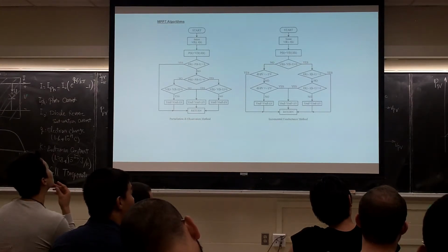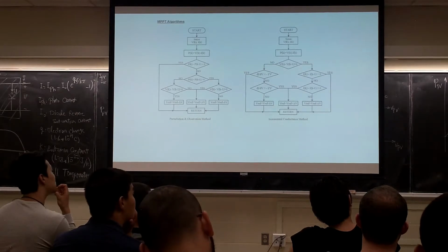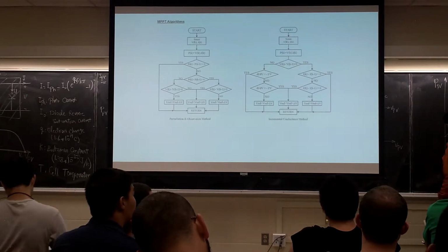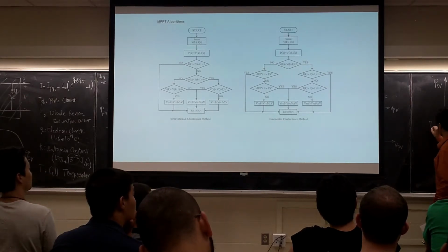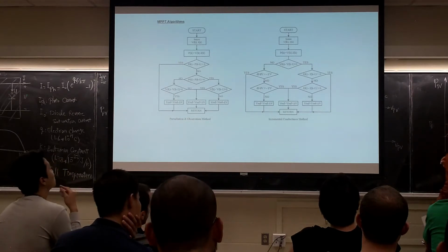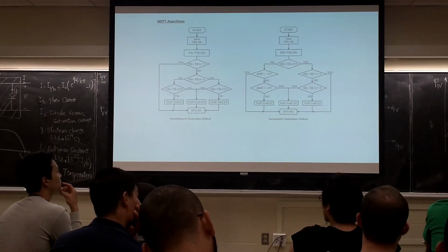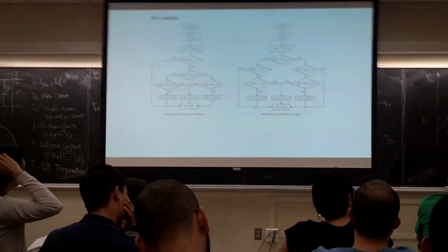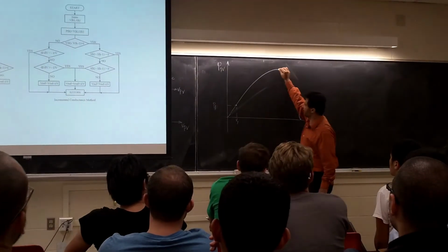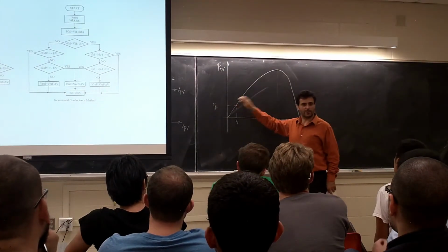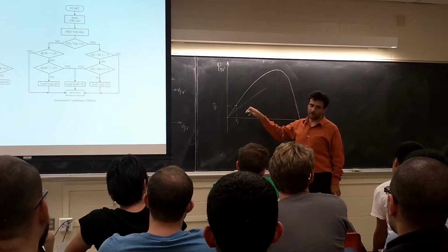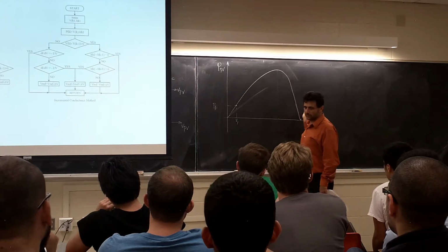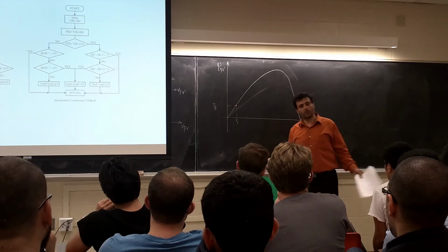When you turn on your PV, usually you start from this point. This is the starting point. Let's call it P1 and V1. At this point, you are P1, V1, right? The first time I'm doing this, I do it blindly. I don't know whether I'm here or here. Either I should increase my voltage or decrease my voltage to get there. If I am here, I should increase my voltage. If I am here, I should decrease my voltage, right? But I don't know where I am the first time.